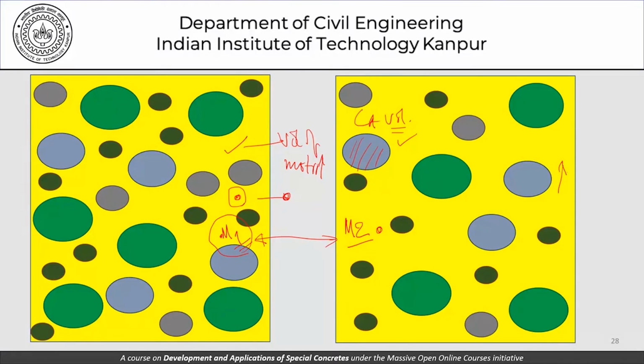So if we control the coarse aggregate volume and of course the particle size distribution involved there from the packing perspective, then we can also get a pointer on what kind of material properties we expect as far as the mortar is concerned. So that is what we get involved with when we are talking about the different ratios in terms of the water powder ratio or the total fines content or the total mortar content and so on.